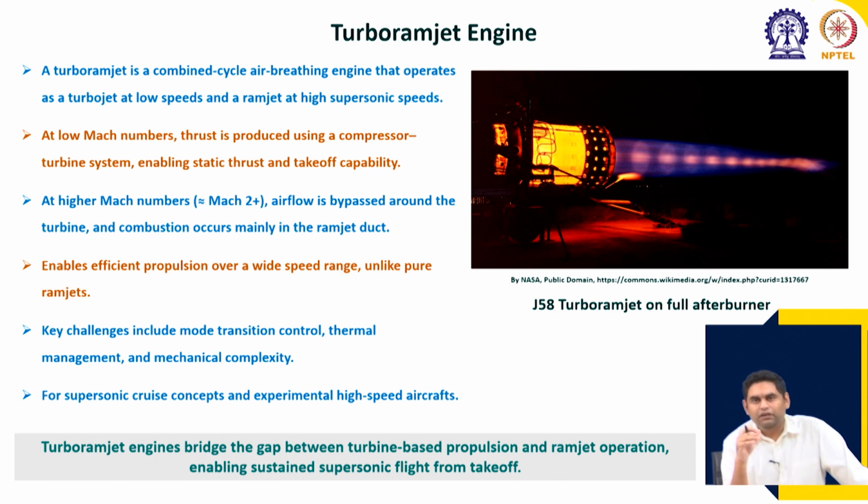We see that ramjets are very effective at high speed, whereas turbojets are more effective at relatively low speed relative to ramjets. Still high speed, but relative to ramjet. And the other issue is that a ramjet cannot start from static condition, but turbojets can. So, the idea of a turbo ramjet is to combine both of these features, so that it operates like a turbojet for moderate conditions, and then at very high speed it acts like a ramjet. Remember that the afterburner works like a ramjet.